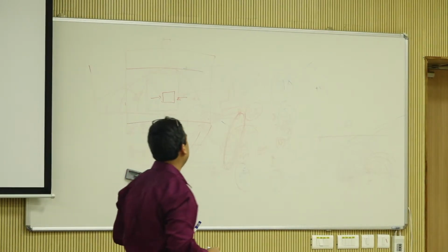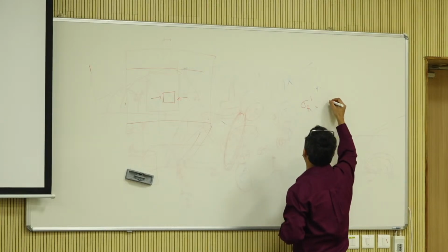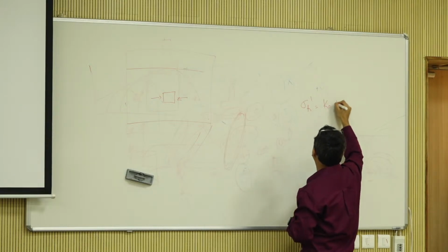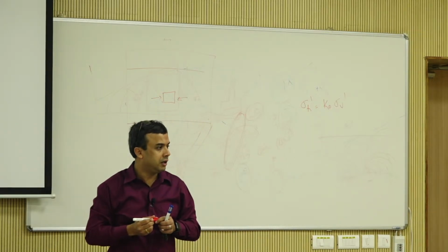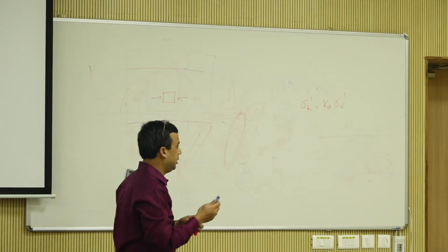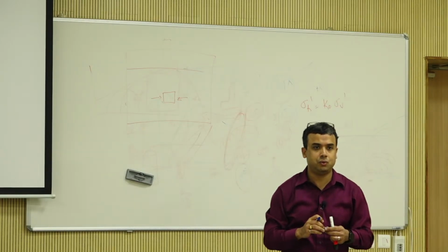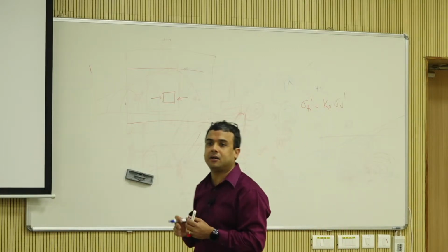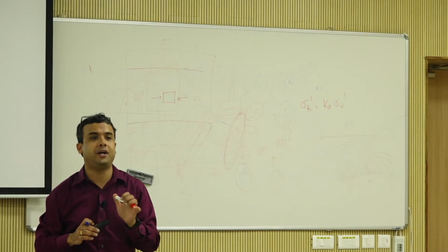And what is that? You geotech folks, do you remember sigma h prime is equal to what? How do you go from vertical to horizontal? K naught, right? Coefficient of lateral earth pressure. So you do that, right? So the question is, why is the unconfined compressive strength test still representative of what you are trying to do?